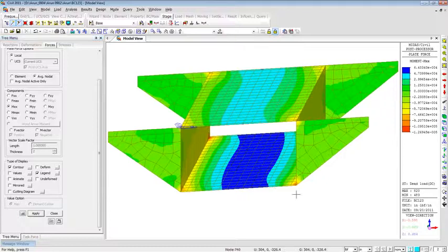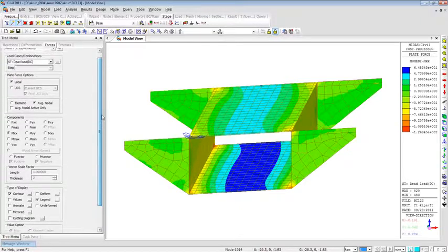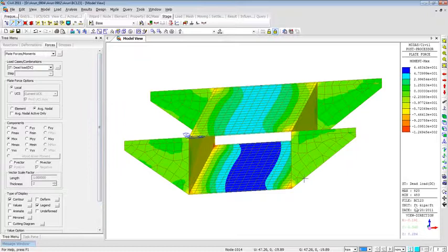So if you can see here, this is the loading value. Let me change the units to inch foot or foot kips. So now you are seeing the plate forces, and the units are foot kips per foot. So per unit length, you can see the display of the forces that are there, and you can very easily generate the plots also on the same contours.